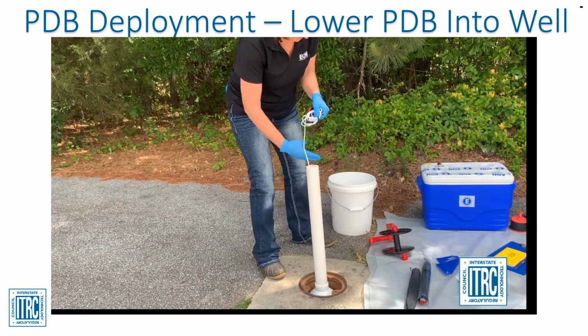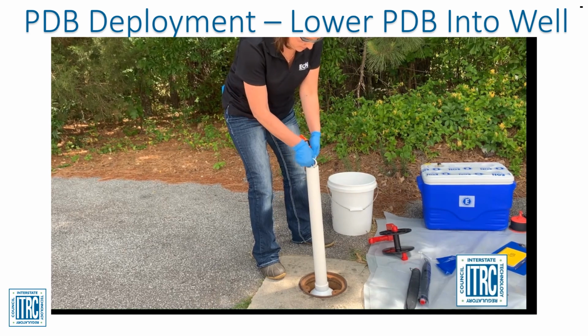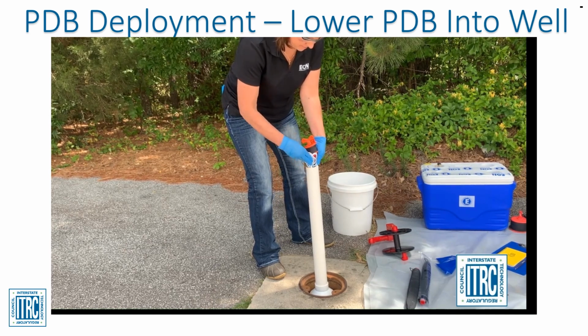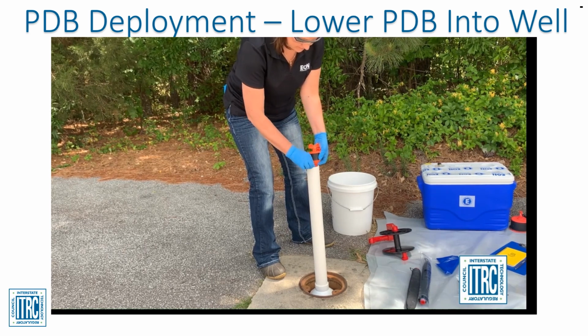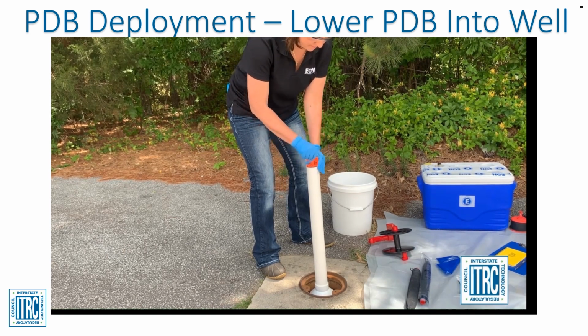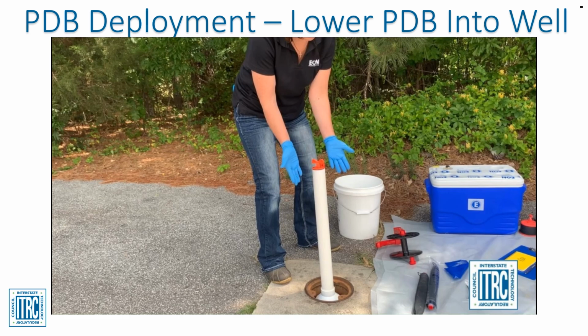If there is extra tether above the well cap connection, gather it together and place it in the well below the well cap. The extra tether can be zip-tied for neatness, or removed if there will be no future depth adjustments. Do not place the tether between the well cap and casing, as this could allow surface leakage into the well.